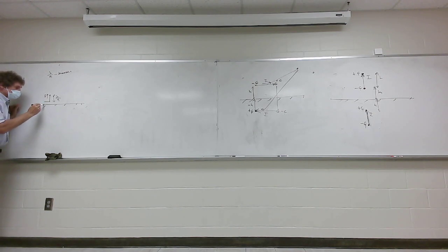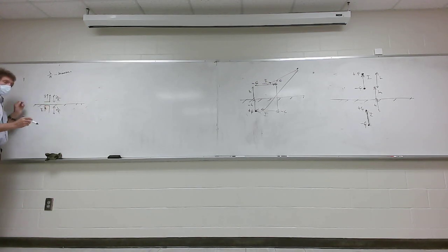And it would image the other half of the antenna, right below that ground plane. This image would have a current I below it. It would be a quarter wavelength long. And guess what? Because it images down here, it looks like an actual lambda over 2 dipole.